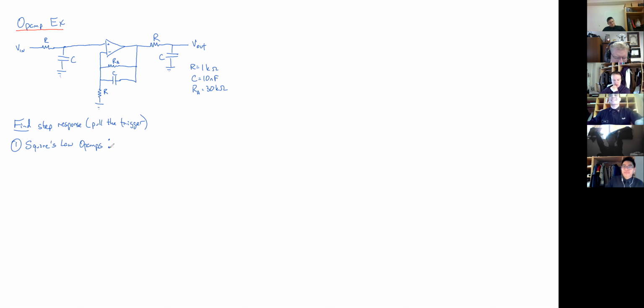And what is it, KVL or KCL? The KVL. Oh, you're killing me, Smalls. KCL, all right. It is KCL and at the inputs. You can't do KCL at the outputs, because despite the fact that it's not shown, there's really hidden power things here that can allow any kind of current to come out of here.